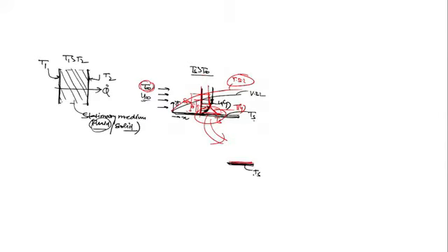This is at temperature Ts, and any fluid layer here is also at temperature Ts. Let's say Ts is 100 degrees Celsius, and the red is the fluid flowing over it, and the different layers of the fluid are there. One layer, this is another layer, another layer, and all the layers of fluid are at different temperatures. It's 100, it's 98, it's 96, like this.